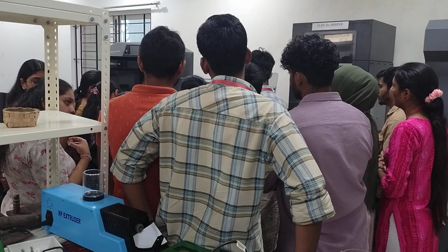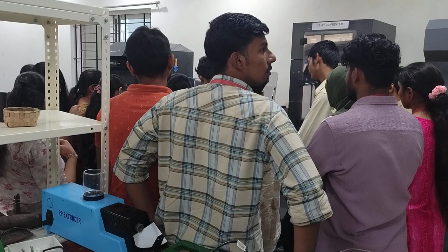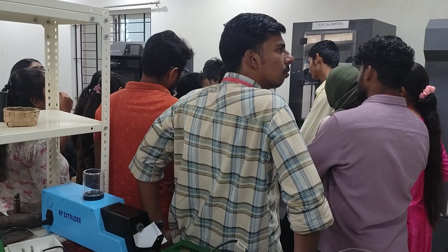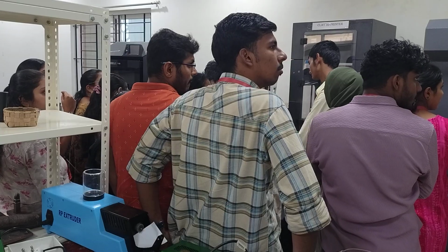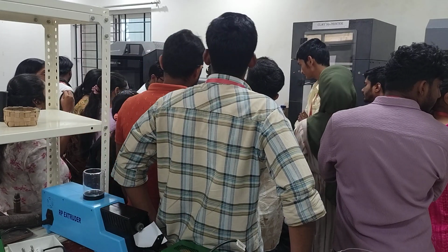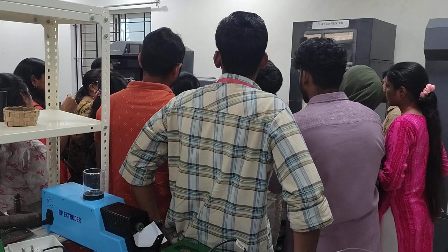It is telling, press next to continue. This touch is not so good, so press once and wait for it. Okay, what is it telling? Cut the filament from the inlet side of the extruder and remove the bowden tube from the outlet. So, the filament from the inlet side of the extruder.